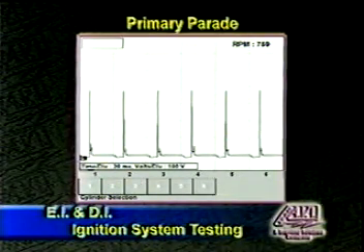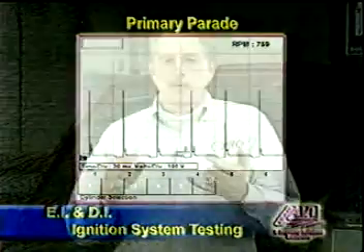You'll notice that all 6 cylinders are uniform on the inductive kick, or what some people call the firing line voltage. At any rate, we know that the secondary loading effect is uniform between all cylinders. And just like a parade secondary pattern, a parade primary pattern only gives us the benefit of looking at a voltage value. The spark lines are too compressed to make any kind of diagnostic decisions.